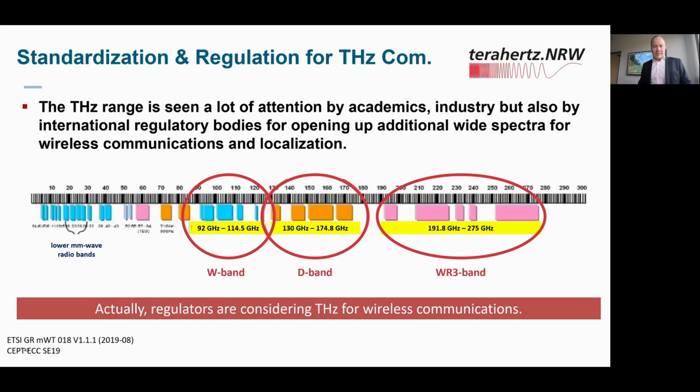So we have different semiconductor technologies, and that means we need a hybrid integration from an indium phosphide laser chip to this silicon nitride beamformer chip to the photodiode chips, which are again on indium phosphide. And this still creates a couple of challenges. We are working on this to have hybrid integrated photonic ICs. You already mentioned this new workshop on photonic ICs, the upcoming workshop here. So we are working on it, but it's still a technological challenge.